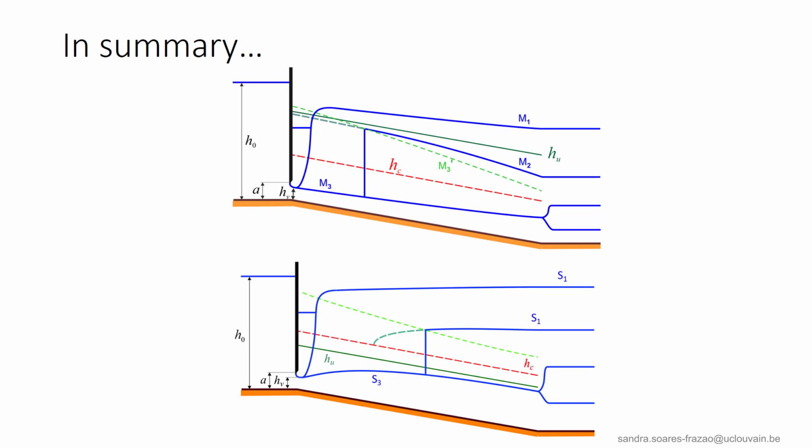So we have seen that there is a great variety of possible solutions for the flow between an upstream underflow gate and a downstream reservoir. In any case, the calculation starts with the discharge and then the normal and uniform depth to know the type of profile. Then, the final solution will depend on the downstream boundary conditions, with a possible trial and error procedure in the case of a submerged hydraulic jump or a flow detachment at the gate.